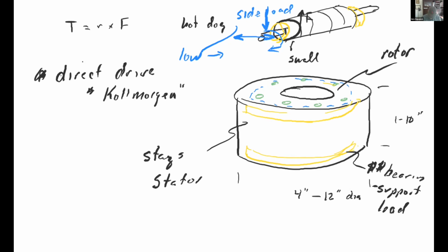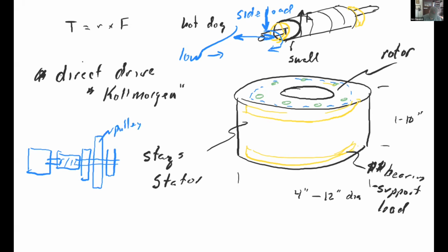You would do a motor and the motor shaft, and then you do a coupler, and then you do something like a bearing and another bearing. And then in between there, you might put your pulley. So it's tempting to put the pulley right onto the motor, but that's F. And F then creates force against the motor shaft bearing. It has to push against something, right?